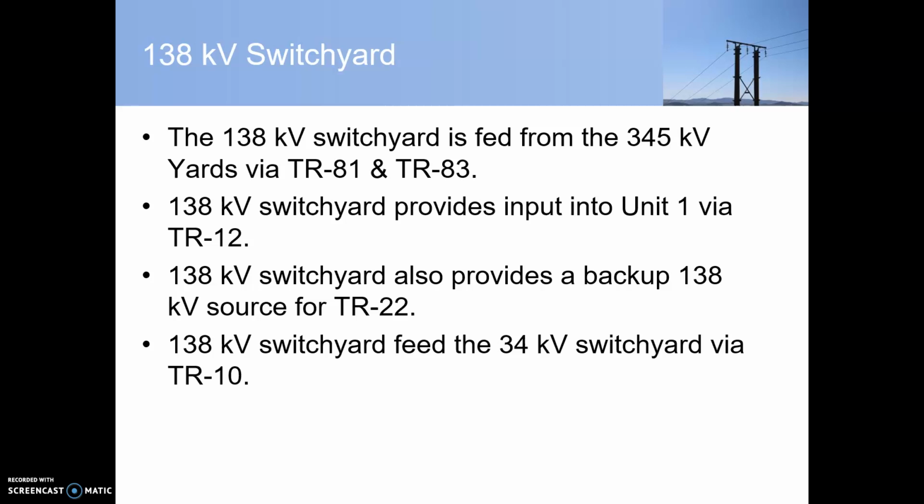The 138 kV switchyard provides input into Unit 1 via transformer 12. The 138 kV switchyard also provides a backup 138 kV power supply for transformer 22. Finally, the 138 kV switchyard feeds the 34 kV switchyard via transformer 10.